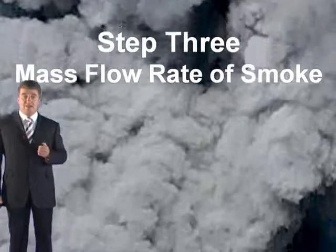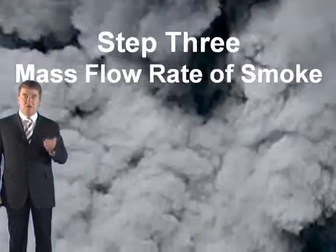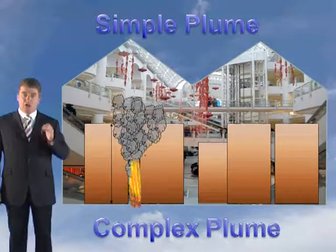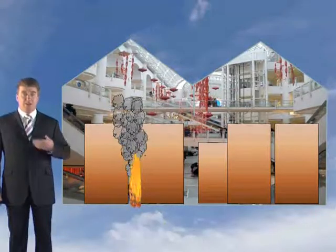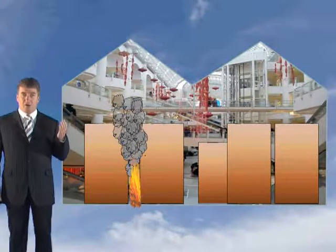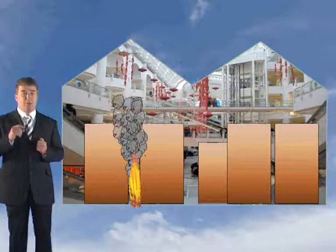Now step 3 is determining the mass flow rate of smoke. You know your size fire, how much smoke is that going to give off? Well, first of all, you've got to establish whether it's classified as a simple or a complex plume. Well, in this case, we know the design fire is actually located in the reservoir where it's going to be extracted, so it's a simple plume. So that's the model for a simple plume.